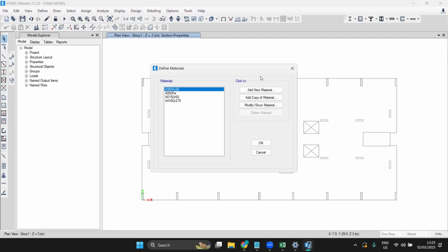The two things are very critical: one is deflection, the other one is punching. Bending reinforcement automatically shows, because whatever the bending moment is, it will reflect with corresponding flexural reinforcement. But punching, always cross-check in another software. I'm not saying SAFE doesn't do it, it will do it. But punching is too critical compared to flexure. So always try to extract the reactions the way which we did. Definitely you're not going to do it.